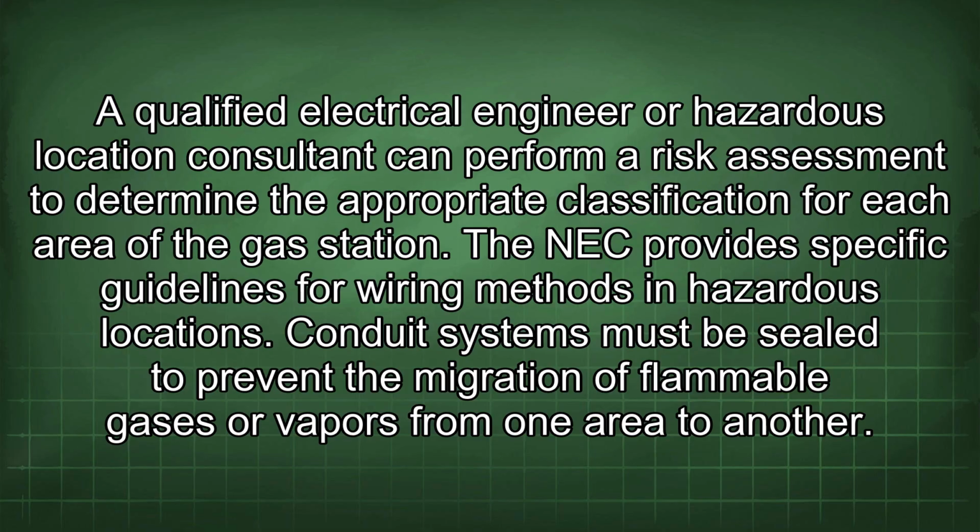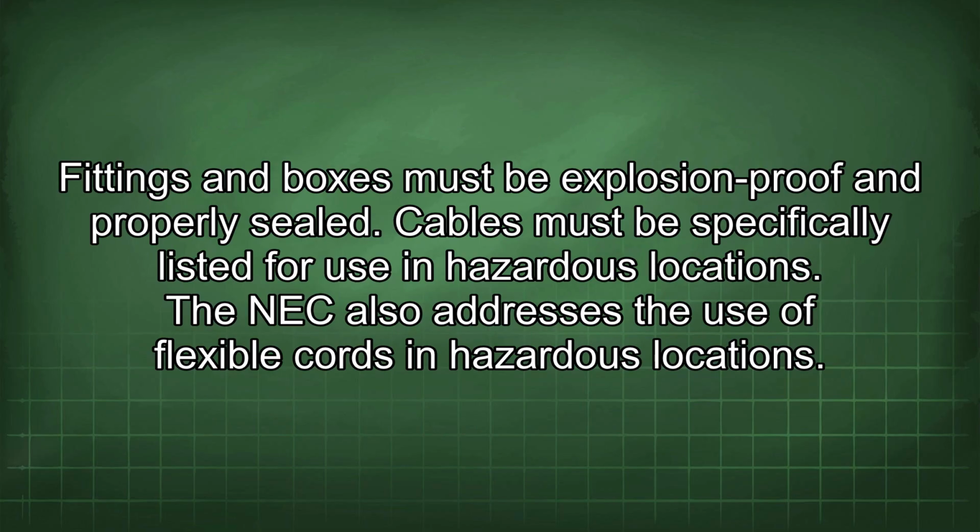The NEC provides specific guidelines for wiring methods in hazardous locations. Conduit systems must be sealed to prevent the migration of flammable gases or vapors from one area to another. Fittings and boxes must be explosion-proof and properly sealed. Cables must be specifically listed for use in hazardous locations.